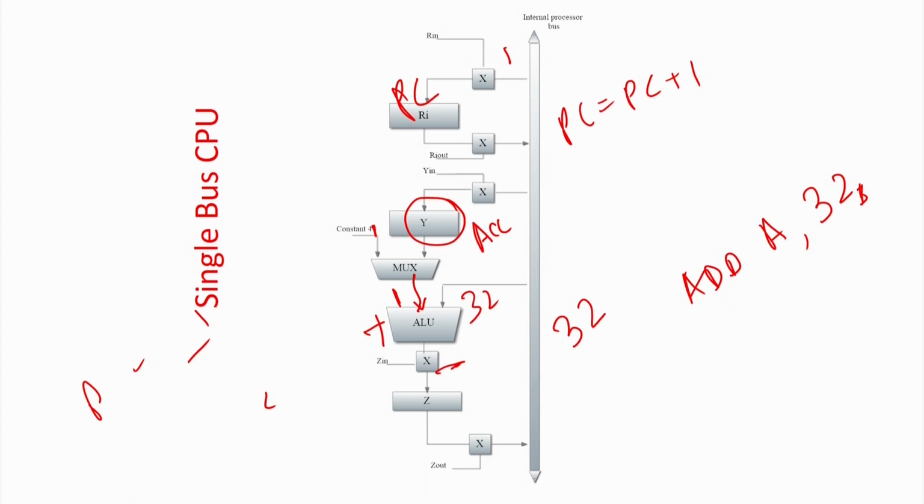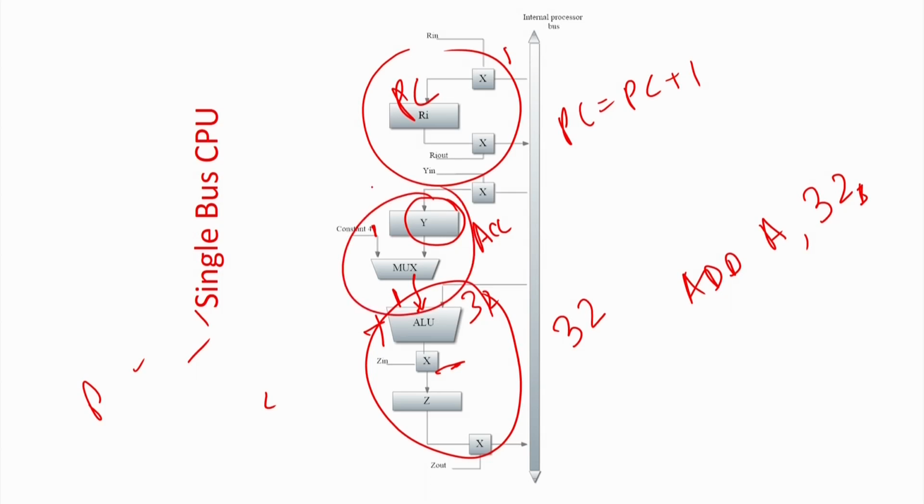So, this is basically the single bus architecture. We have some registers which have input and output control, that is, a register can be fed in, and a register can be fed out from the control bus. Similarly, this is an ALU. The ALU also has the facility that you can load and also write out the value of the ALU to the control bus, and we have a multiplexing arrangement. In one part of the multiplexing arrangement you can take some operand from the control bus, and the other operand is a constant, like increment by 1 or by some other constant value.